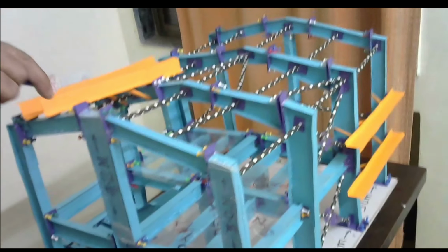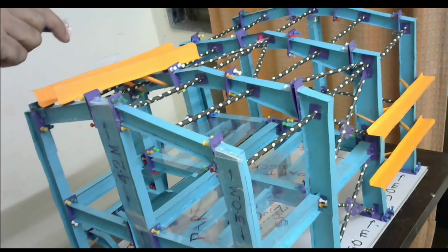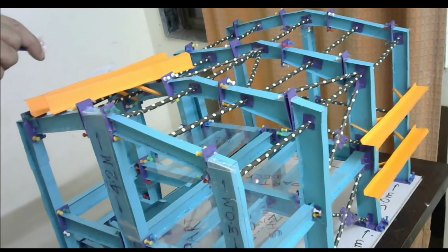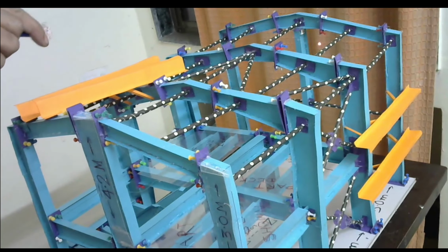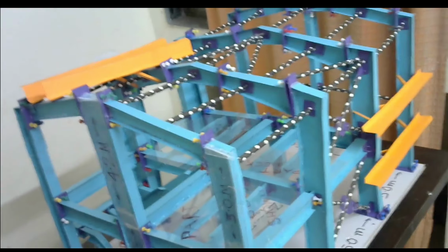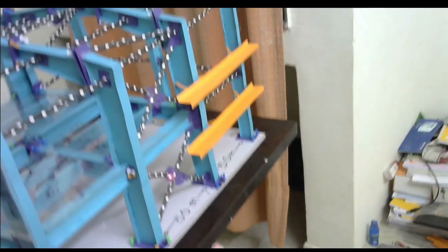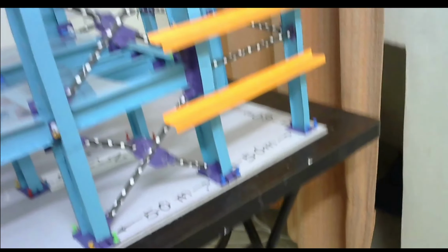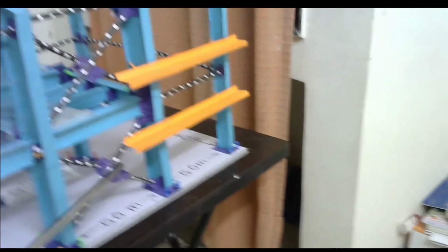Now let us come to the bracing. For the braces, the factor will be node to node distance, which means if there is no node in between, we do not need to define it in STAAD. If you see this bracing, there is a connection here, here, and here.